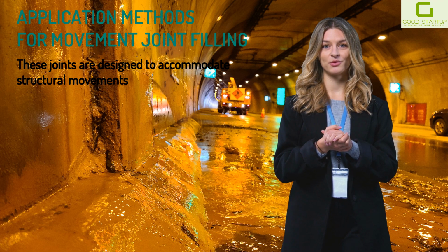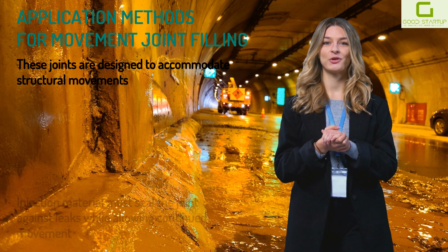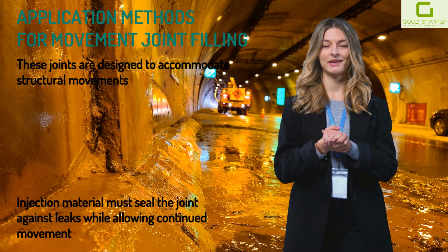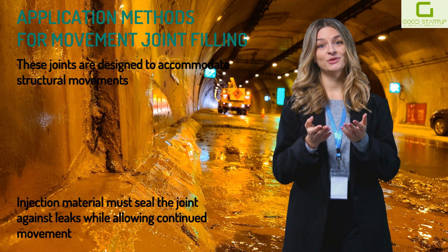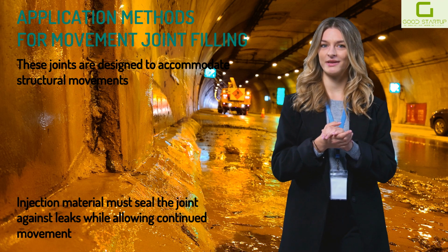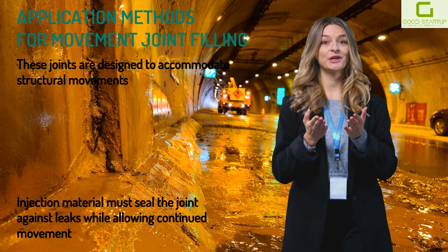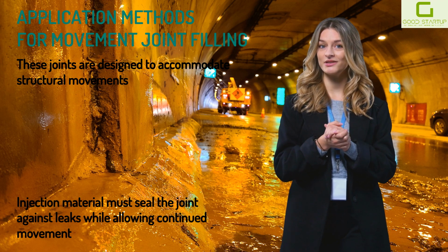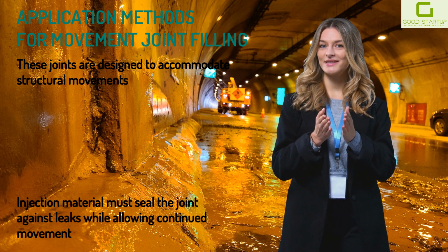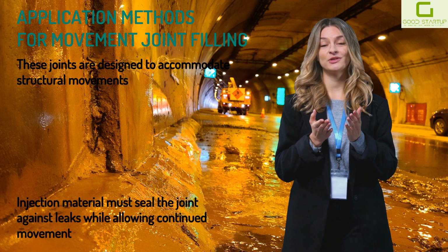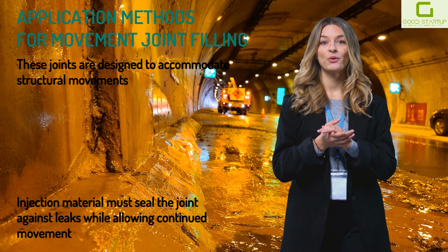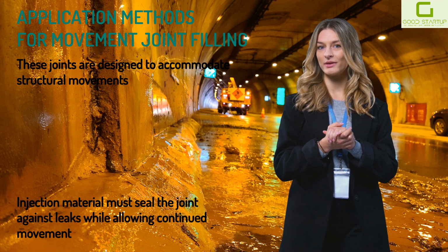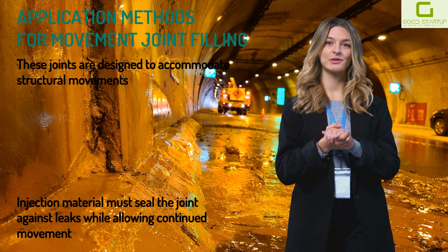Application methods for movement joint filling. Movement joints, such as expansion joints in concrete structures or segment joints in tunnels, present a unique challenge for sealing and injection. These joints are designed to accommodate structural movements, expansion, contraction, or settlement, so any repair or injection material must seal the joint against leaks while allowing continued movement.